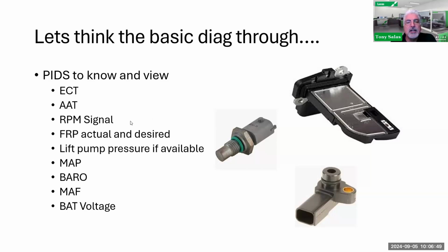So Matthew, you asked me real quickly, I'll get to that here. You asked me a question of how the restricted exhaust affected rail pressure. The engine was trying to run, but since it couldn't exhaust, it started to build up a lot of back pressure to the point that the engine was starting to lug down, and terminally lugging down. The RPM went down, and the pump wasn't turning as fast, not generating the rail pressure, until eventually it died and rail pressure dropped. So there's your answer, sir. Hopefully that answers your question.